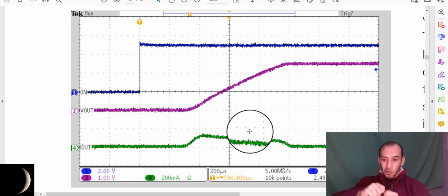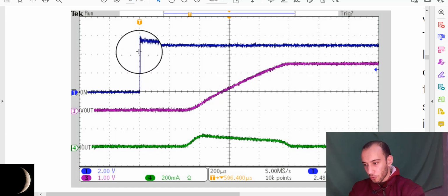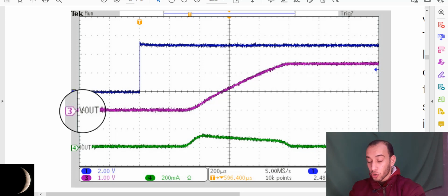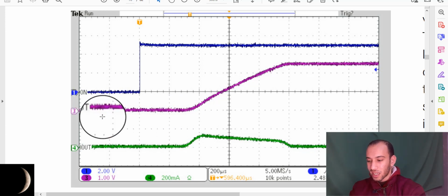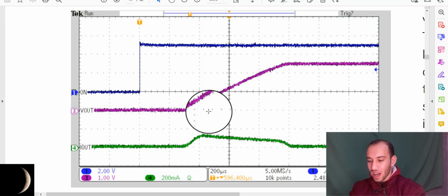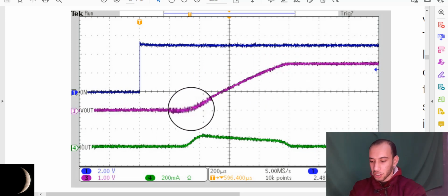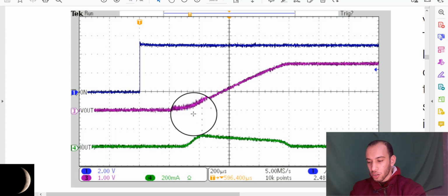You will turn on the MOSFET slowly. So this is the input voltage, the hard transition of input voltage. When you control the turn-on time of your MOSFET, you will get this curve of Vout, a smooth transition, and this is the target we're going to make.